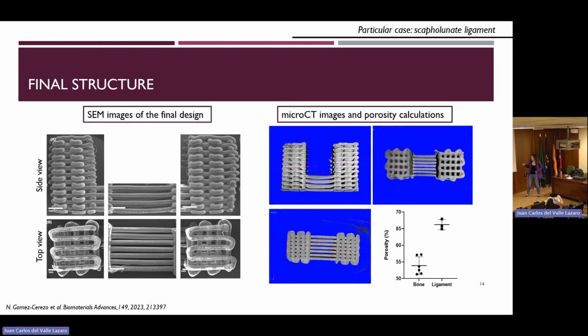Everything is very well thought out here, because we have 7 struts in 5 millimeters. If we had 8 struts, it was too thick, so the mechanical properties and the flexibility were much lower and it wasn't as good. And if we had just 6, it was too soft. So 7 was the optimized result. In terms of these 7 struts that we have in the ligament part, we did a few studies with the help of Natalia with the simulation. She helped a lot. And that's why we have this porosity.